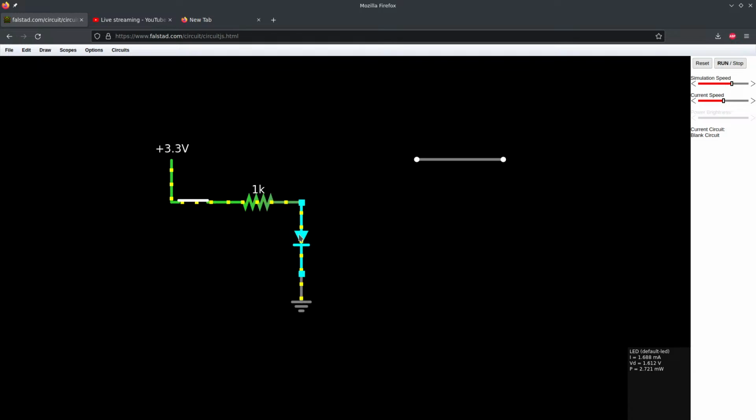The way you would find out normally is by looking up the data sheet. It will tell you what the voltage drop will be at the rated power. Usually this would be like 2.2 volts for a red LED, which is pretty common.